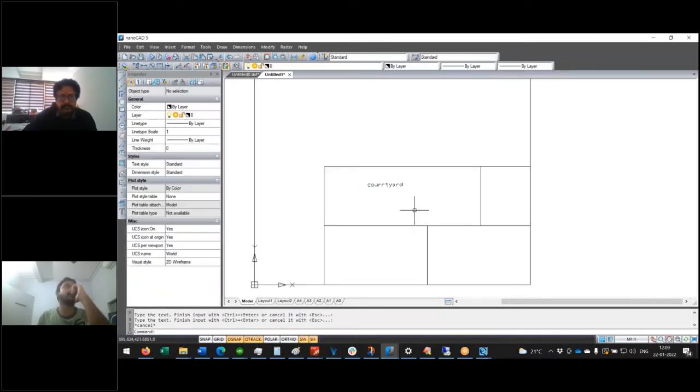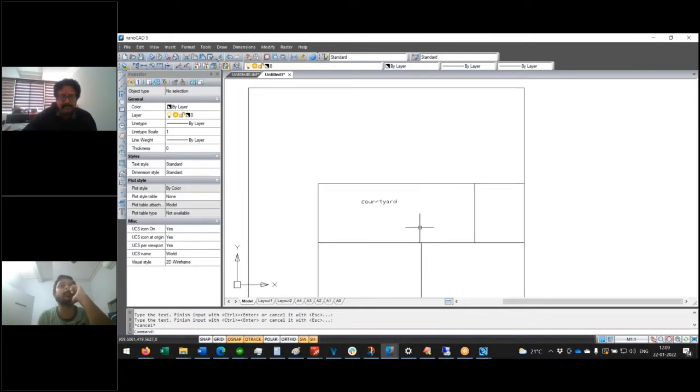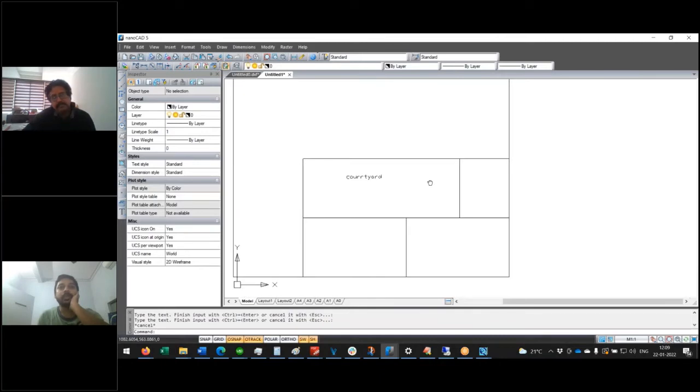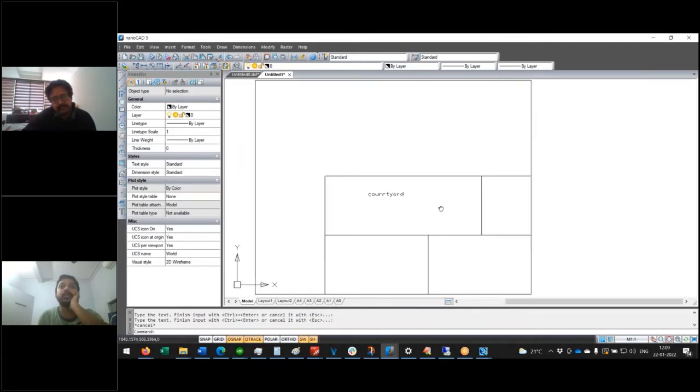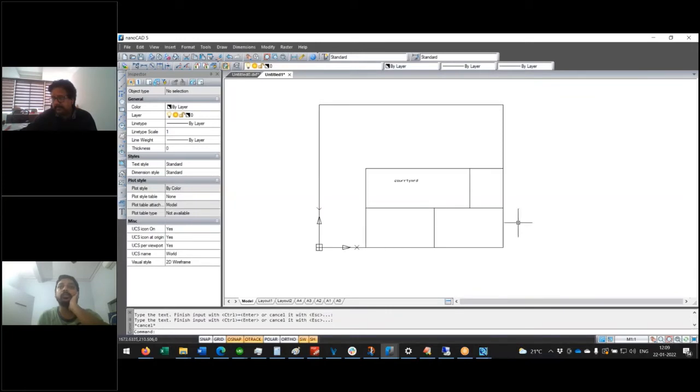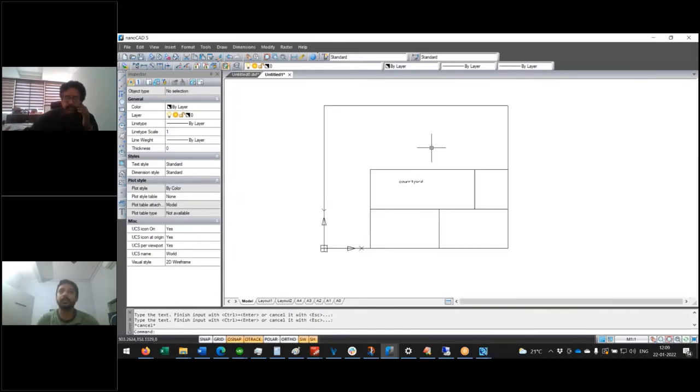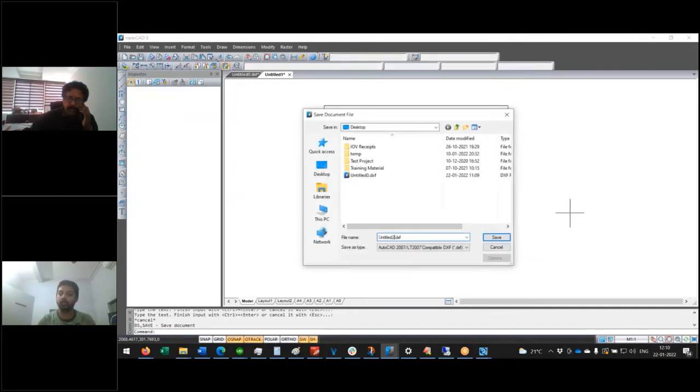Yeah, right. So Mr. Rizwan asked how to create a courtyard in the middle of buildings. Let's say this is your courtyard. How will you model this? In that case, what you have to do is break the entire building into two parts. There are two ways of doing it. One is creating one single shell like this. The other is to create two shells. Okay, two building shells.